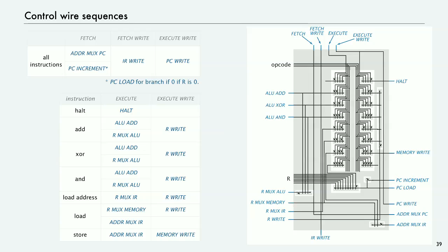And then for each instruction, there's logic, for example, the arithmetic instructions. Add instruction is opcode 1, so the second gate down in the multiplexer is the only one that turns 1, so it turns on ALU add. And then it also needs to select the ALU line of the register mux.